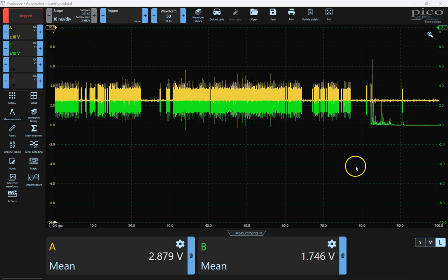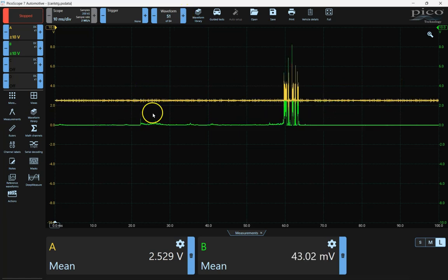Okay, so this is another machine which is actively terminated. Intentionally I shorted CAN low to ground. We can see out here when that happened. I tried to make it like an intermittent short, so sometimes I was briefly making contact, as in this case. If you recall from passive termination, if I short CAN low to ground, there's a good chance I might not even know that it happened because CAN high is still able to drive up to the dominant state. With active termination, this is not possible.